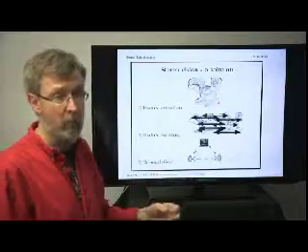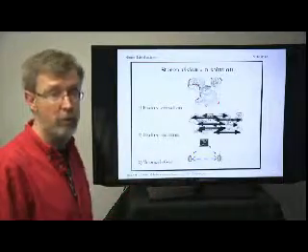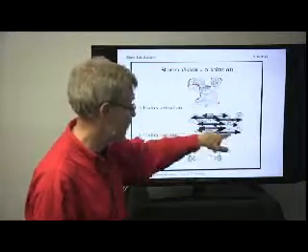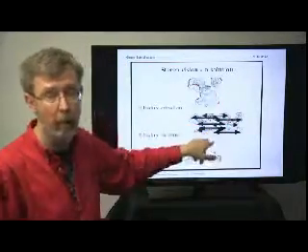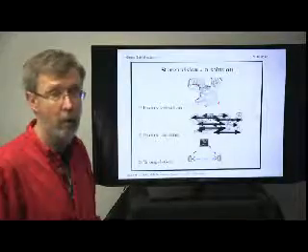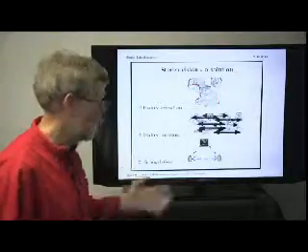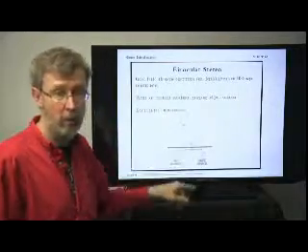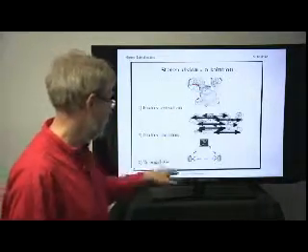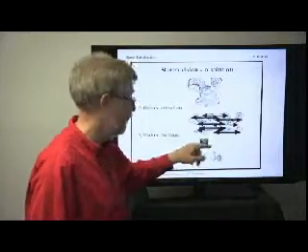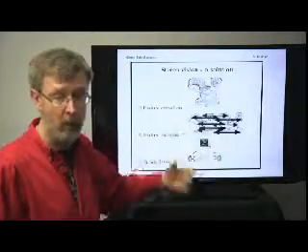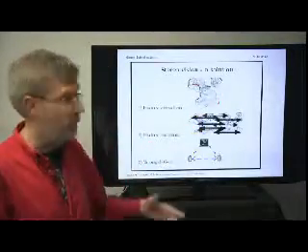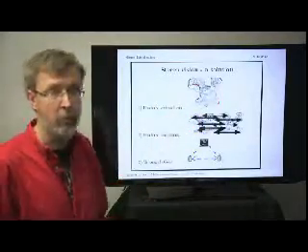Once we've done that for the left and right image, now we have to match up the features between the left and right image. So we want to establish some kind of a correspondence, shown schematically by these arrows right here. And once we've got the paired features, then we can do this kind of triangulation that we've done in this simple geometry. And we can calculate where that feature is in the three-dimensional scene. And we do this for each of the features. And that's what builds you a three-dimensional description of the scene.